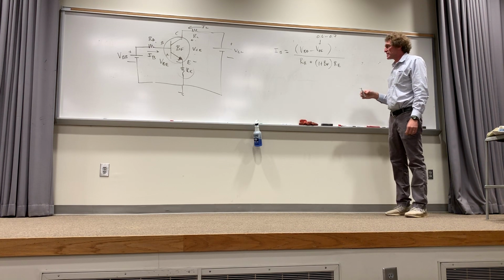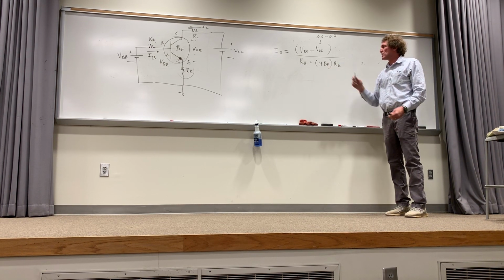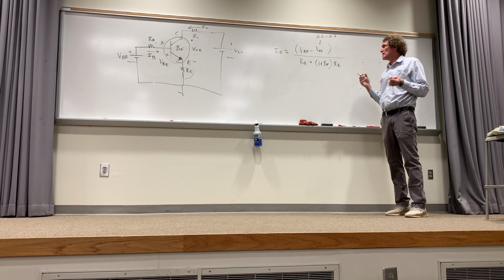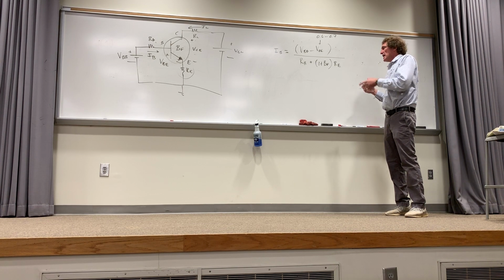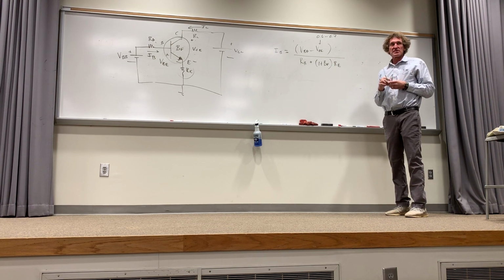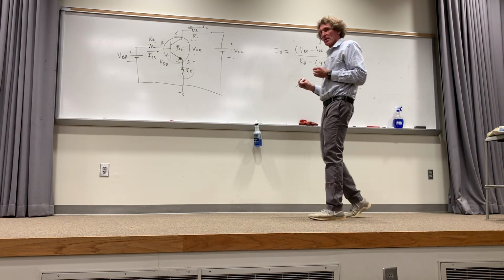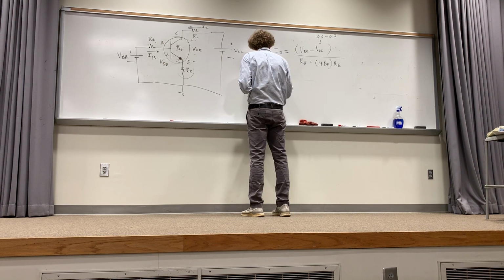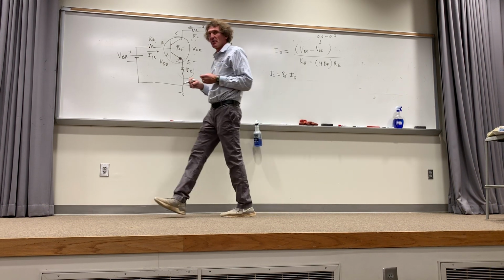Thing to take away from this is now the emitter resistor is amplified by 1 plus the forward beta gain, the forward gain of the transistor, and that's how it's felt in the base circuit. Does this make sense to everybody what I'm doing here? So that limits the current. Now that's the actual base current. Collector current is simply equal to beta forward times I base. You get that just by knowing that relationship.